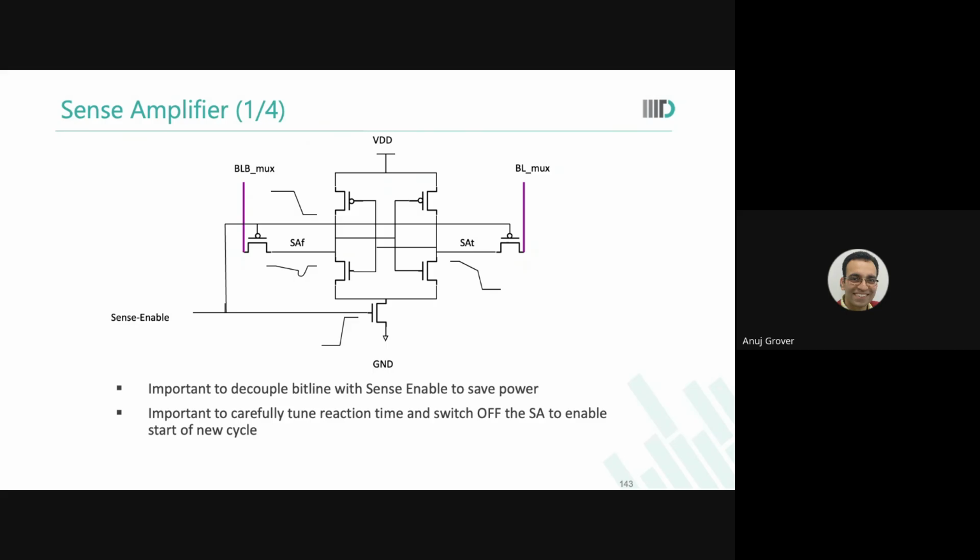And you would see that those of you who do this project on sense amplifier, you would see that if this is SAEN pulse width, okay, so SAEN pulse width is growing, then this will be the way my offset would appear to be. At a very small SAEN pulse width, offset will be large. Offset requirement will be large. What does it mean? For a given reaction time, for a very small SAEN pulse width, I need a larger offset.